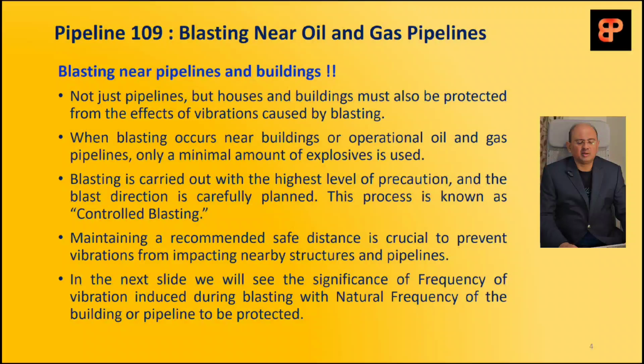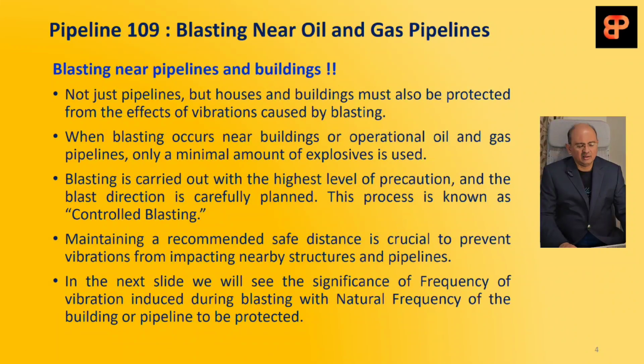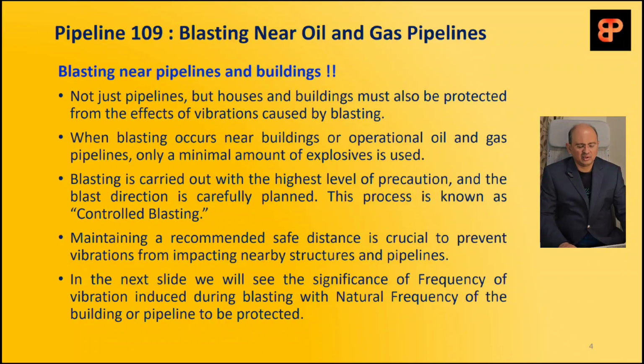When blasting occurs near buildings or operational oil and gas pipelines, only minimum amount of explosives is used. Blasting is carried out with the highest level of precaution, and the blast direction is carefully planned. This process or methodology is also called controlled blasting. Maintaining a recommended safe distance is crucial to prevent vibrations from impacting the nearby structures and pipelines. In the next slide, we will see the significance of frequency of vibration induced during blasting with natural frequency of the building or pipelines to be protected.